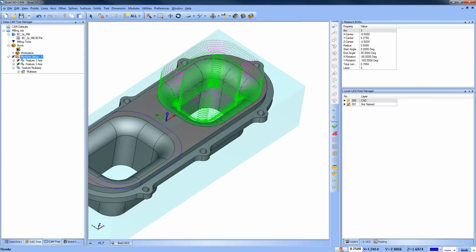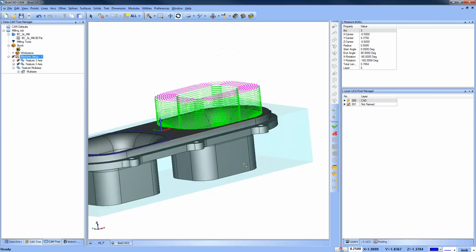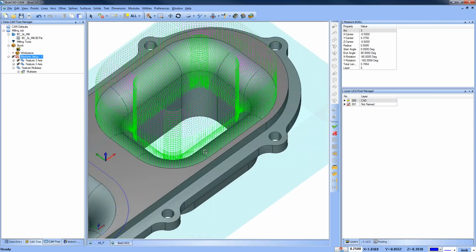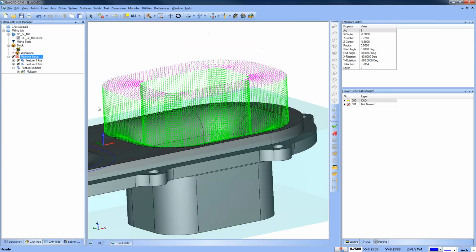Whether it's rotating around Y or X or a C axis, that's not going to play a bearing on whether you would be a Mill Premium or a Mill Pro user. A Mill Premium user is going to give you more toolpaths for 3D machining, kind of like this one here. Now, at first glance, this toolpath is looking kind of strange. We see a lot of retracts happening.